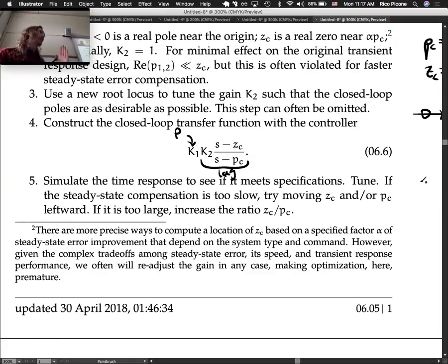So you have the position of the motor, and you subtract, so this is typically done in software now. You subtract the position that you want from that, and then you multiply it by our gain or whatever, and you say this is how much voltage we want to supply to the motor to make it go to the right position. So what you're computing essentially is what input should I give to the motor to make it go to where I want. And if you do this, you could do this in a passive circuit in this case.